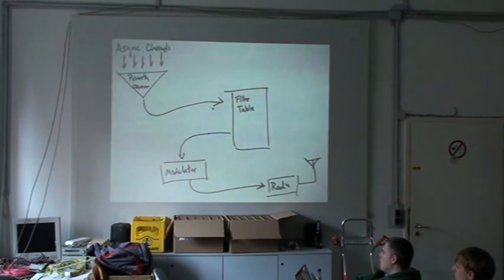So then, when we transmit something, we put a copy of it in the filler table. We put it at the frame number position modulo the multi-frame size in the filler table for that slot. And then if we need to transmit something and we don't have anything available coming out of the queue, we go to the corresponding frame position modulo the multi-frame size in the filler table and get something to transmit.